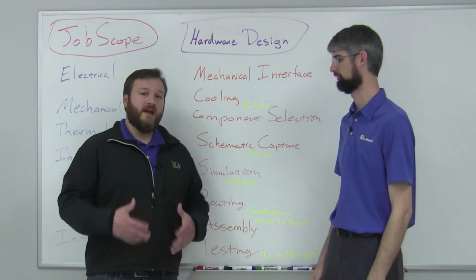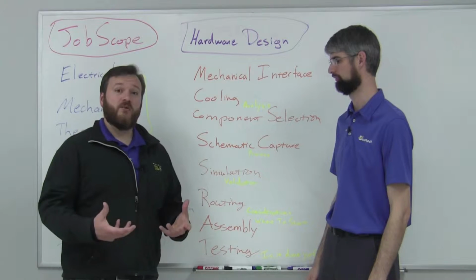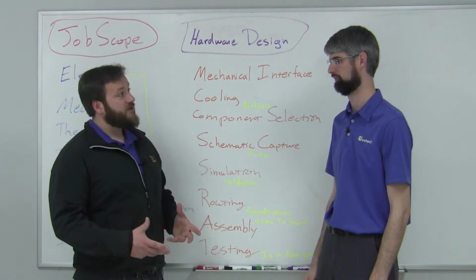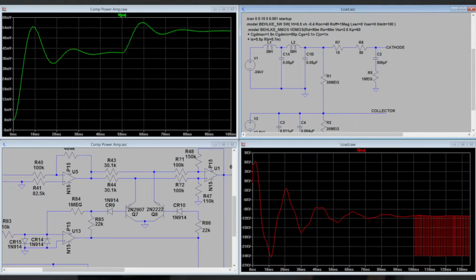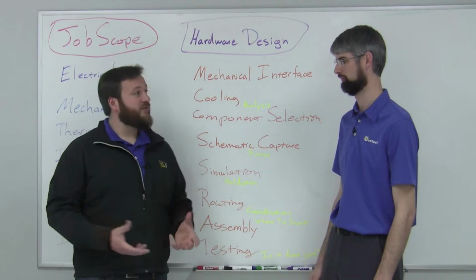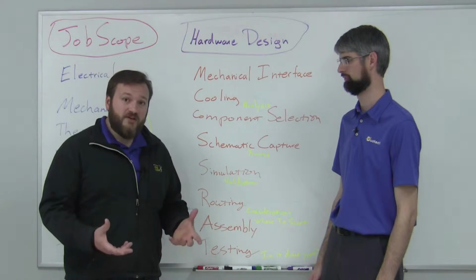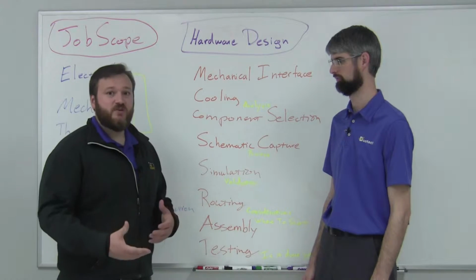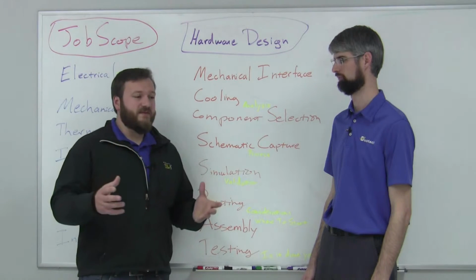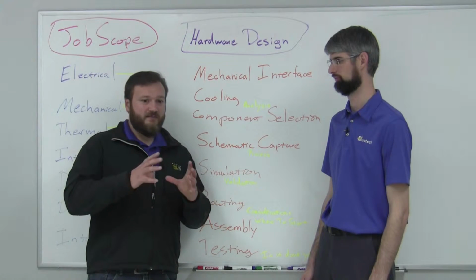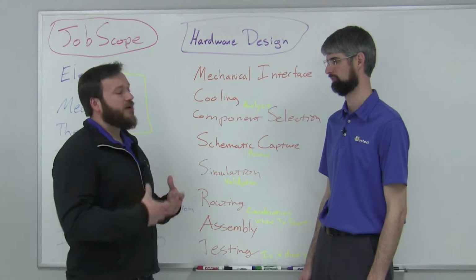Absolutely. And then going from that part into the part where we actually have physical hardware, we go through the step of simulation. In simulation, we may be dealing with very harsh environments. We also may be dealing with very high speed or very small signals, anywhere from femtoamps in small currents up to very high frequency digital buses in the 500, 600, 700 megahertz range, and also RF signals and those types of projects. We have to be worried about a wide variety of things, not just how cold it can be or how much it can shake, but whether we can actually provide signal integrity and a reliable product through simulation.